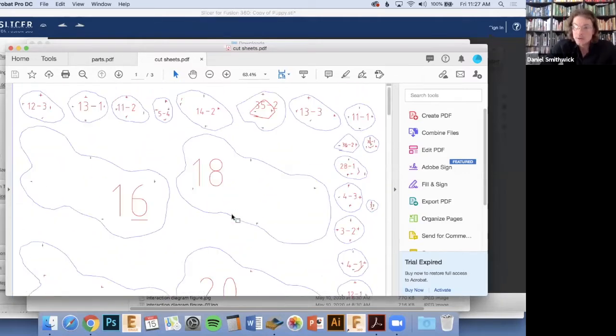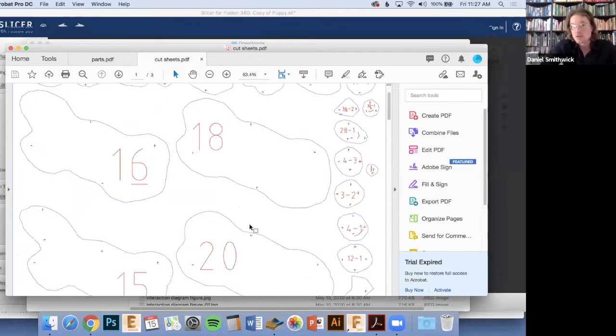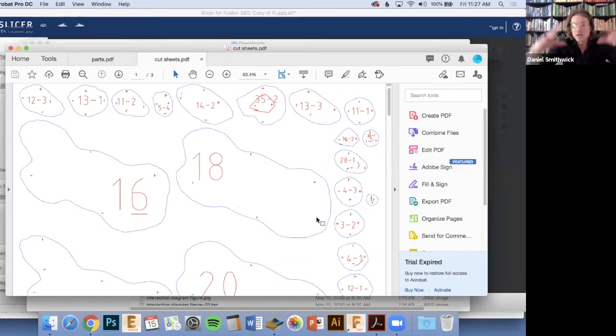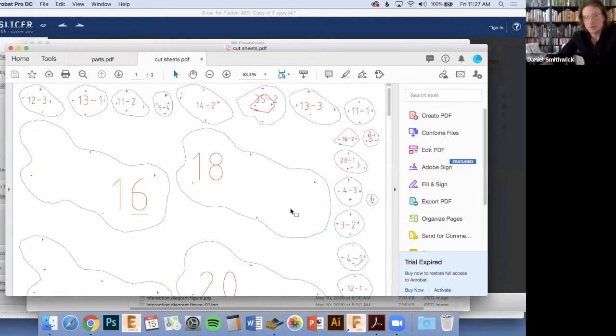I could send this to a laser cutter if I had access to one, or like I did with my lesson, I can send it to a projector and project this on the wall and trace it out. What's neat about that is the scaling minimizes the error. The error that your hand will create becomes negligible. And that's how I did this half pipe here, completely by projecting it to a wall. So you can see it still gets assembled. And that's really the workflow.